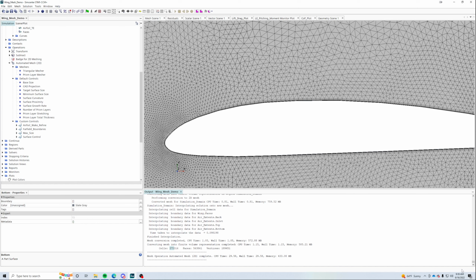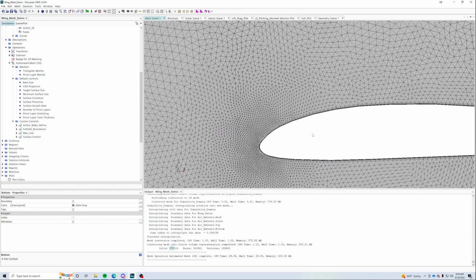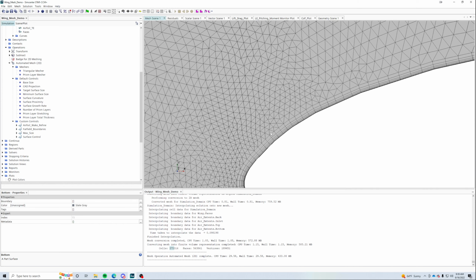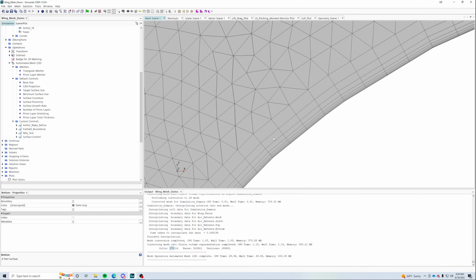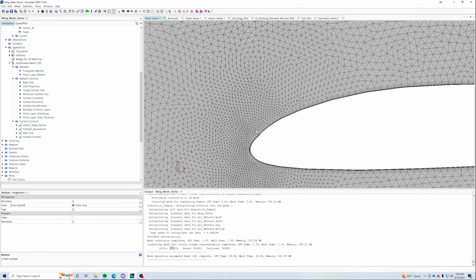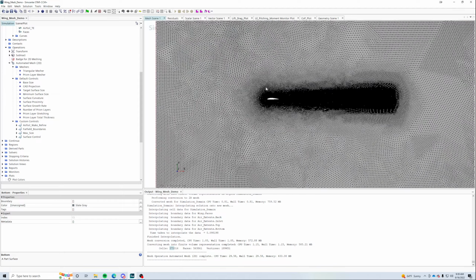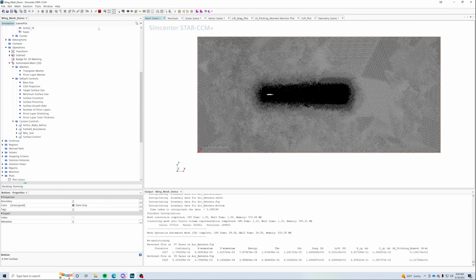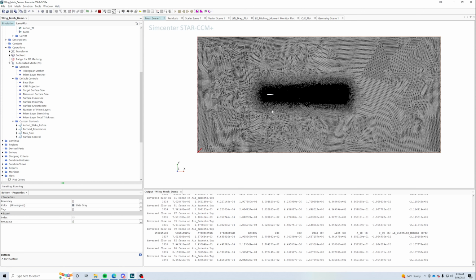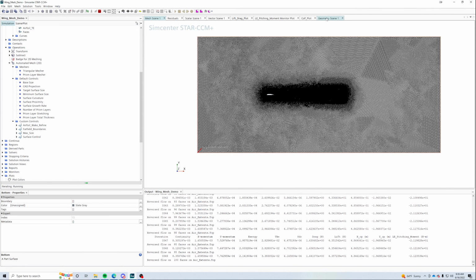This one has pretty much double that, if not more than double that. It's got like 2.5 times the number of cells. So it'll run slower, but it's of pretty reasonable quality, in my opinion. I mean, the mesh settings are all the same, so the cell sizes are principally identical. It's just a matter of we have more of them. More cells means it runs slower.